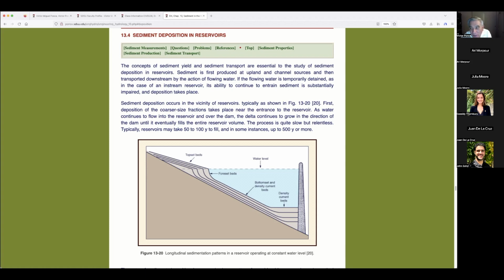So the way to protect yourself or society against this is to immediately after the fire create a reservoir that will hold on to the debris flow. And that has been done successfully, by the way, in many instances. I happen to know of one particular instance in the 1990s, as I said, in the 1990 event. They had a huge fire in July of 1990, and then they had a huge rain in March of 1991.